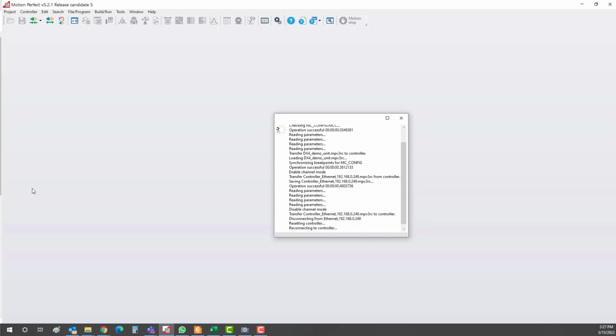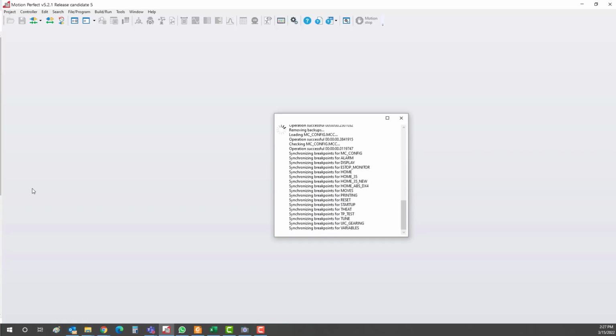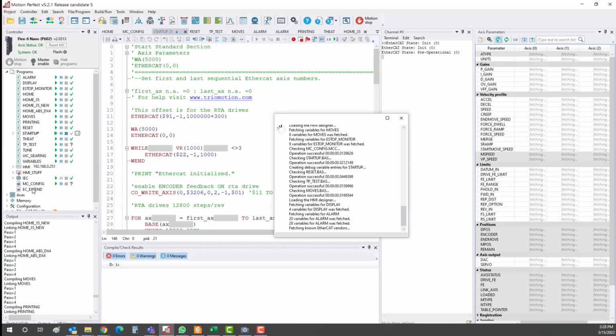And after that, it will create an ECExtend file, which is the additional extension file for EtherCAT configuration, and will attach to your project as a permanent file, just like other programs. And that ECExtend lets the drive have the second encoder and read it over EtherCAT. And it all happened automatically.